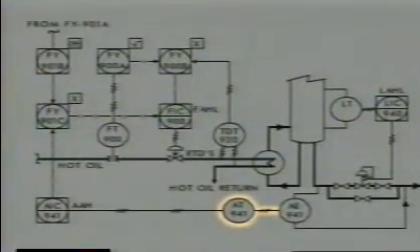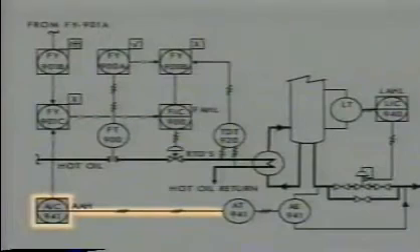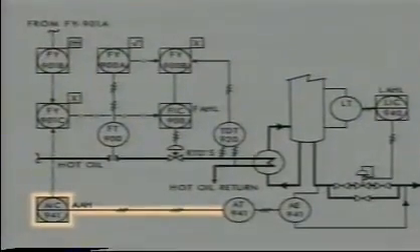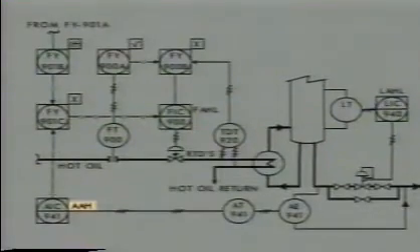This device is also field-mounted. The analysis transmitter sends an electrical signal from the field to the control room. You know this because the symbol for the analysis controller indicates that it has a shared display, shared control function that is accessible. This note indicates that the analysis controller has an alarm that activates when it reaches a high limit.